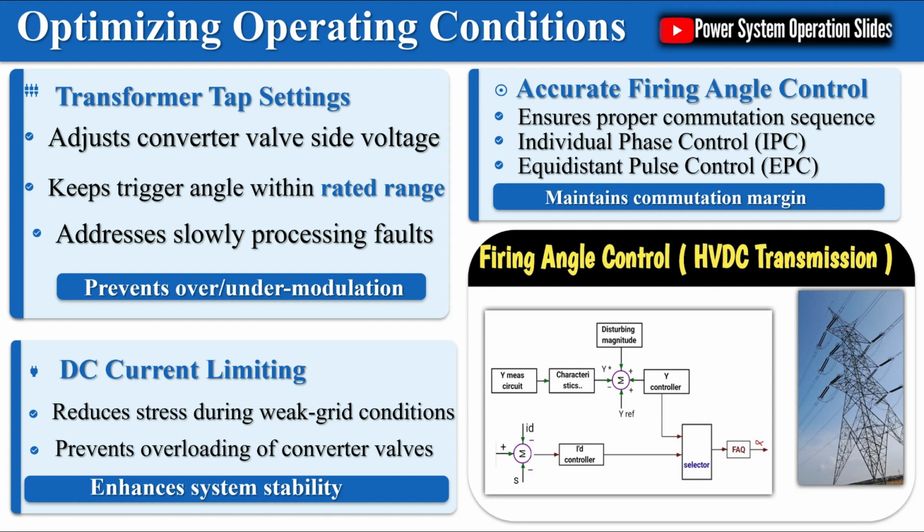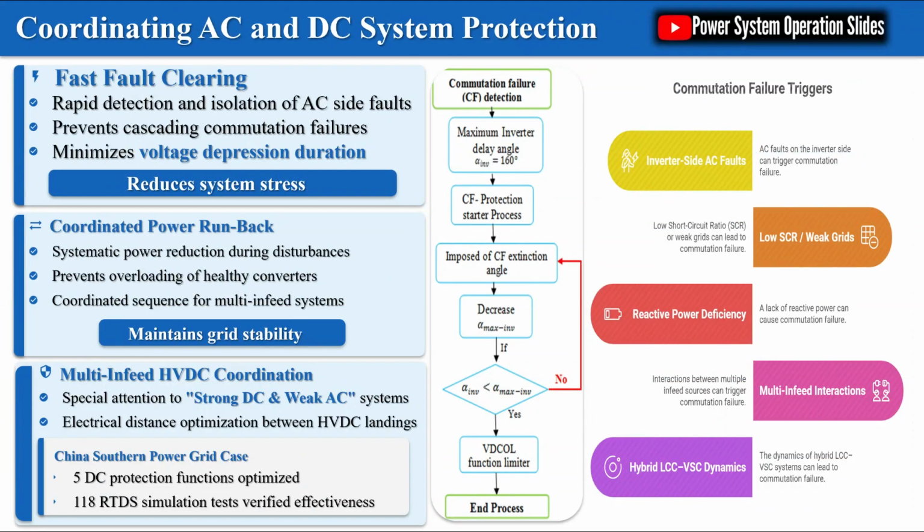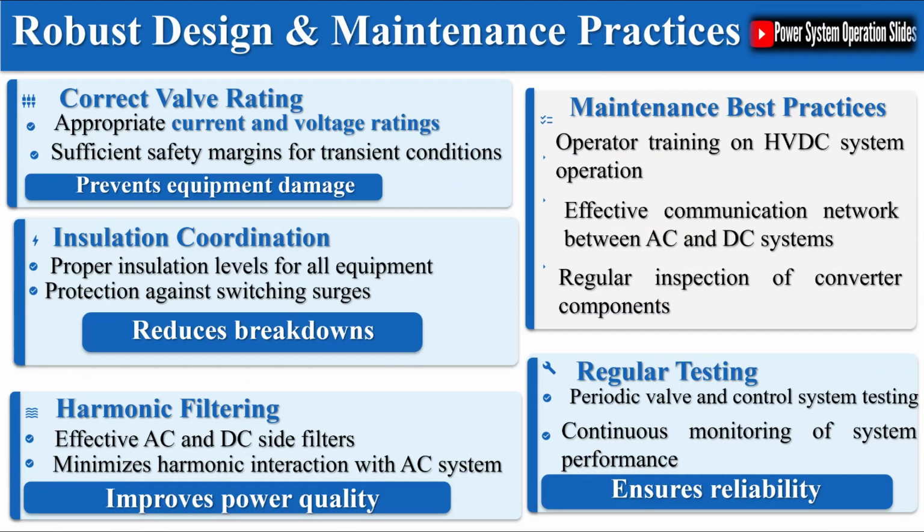Mitigation of commutation failure typically involves a multi-layered approach encompassing 4 major categories: protection and control optimization, auxiliary equipment installation, DC power coordination, and converter structure modification. Key control measures include extinction angle control, EAC, gamma minimum control, current order reduction during faults, fast fault detection and recovery logic, and advanced firing angle during voltage dips.